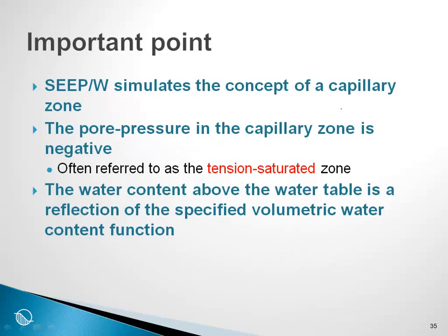So there are some important points here. SEEP-W simulates the concept of a capillary zone. The pore pressure in the capillary zone is negative, but in the capillary zone it's negative but saturated, and as a result we often refer to this as a tension saturated zone. Lastly, the water content above the water table is a reflection of the specified volumetric water content function.